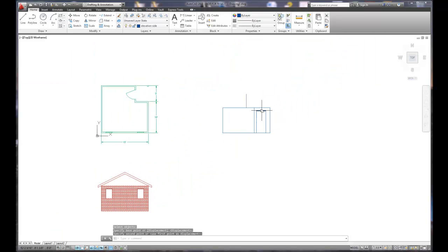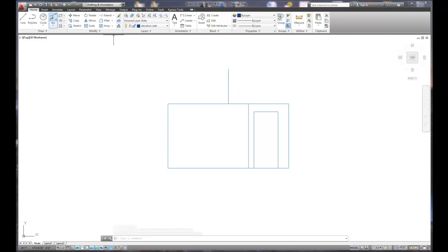Now, overhang wise, we know that's the height of the roof, and we know that it comes out 1 foot. So I can draw a line in 1 foot or 12 inches, bring it up to this height, bring it across, and then stop. Notice that I made the line extra long, bring it over 1 foot, bring it straight up. Oh, I actually brought it over 1 foot without drawing the line in. That happens sometimes. And then fillet that corner.